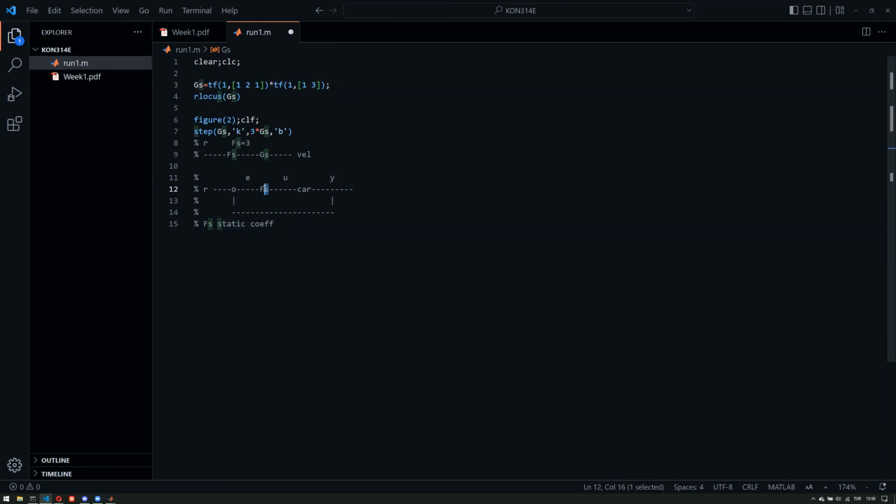Now, for that same reason, if you're considering the root locus plot, what you do is you just place a k, because it's a coefficient, so let's call it k. Now, we can calculate the resulting closed loop transfer function, and that's going to be one of our steps, because we need to determine what the closed loop transfer function looks like.